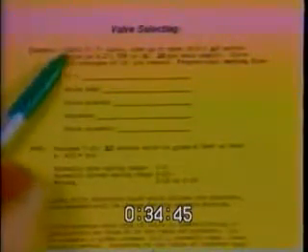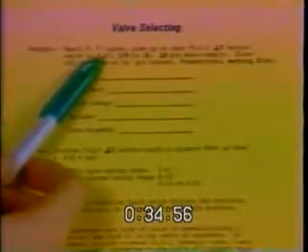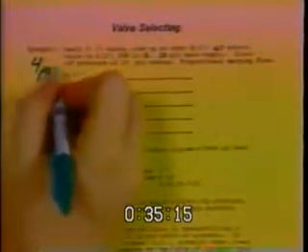Now we're ready to select a complete valve assembly. Let's go through a problem so you can see how this is done. The example here is as follows. I want a small GS, that stands for globe screwed, valve. Stem up open, or that's a normally open valve. Pressure drop across the valve is going to be 9.2 feet. Now 9.2 feet, if you were to multiply that times 0.433, you'll come up with a pressure of 4 psi.